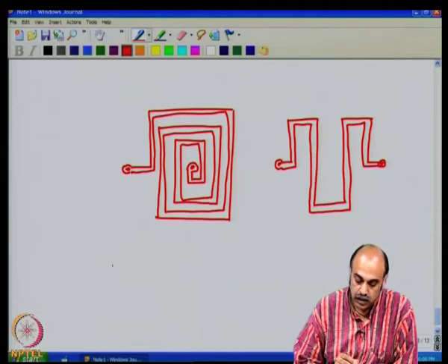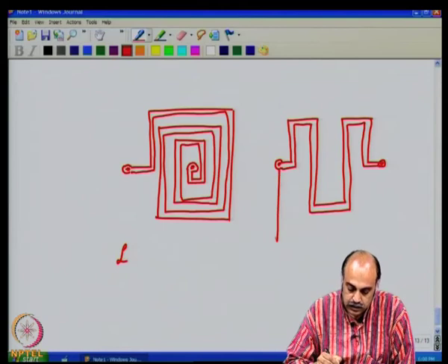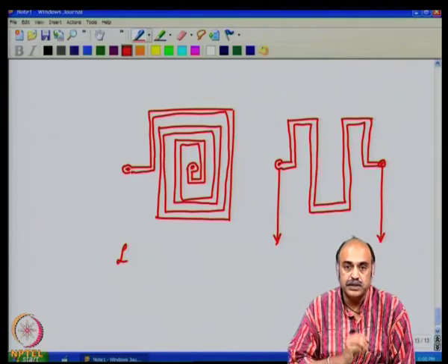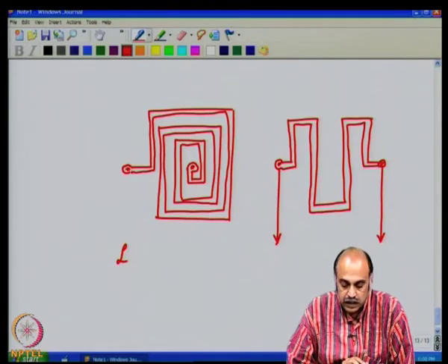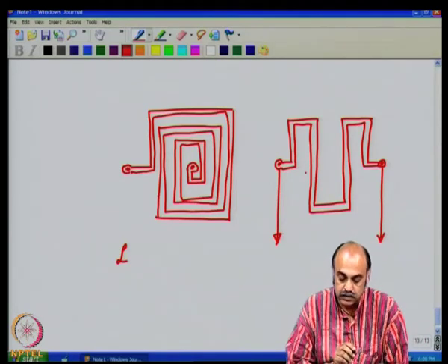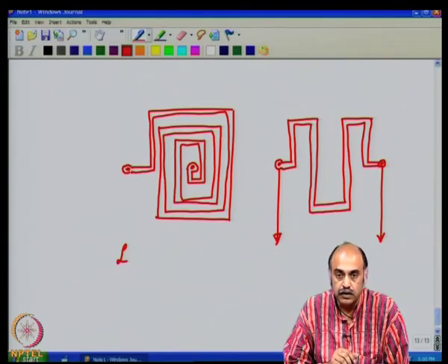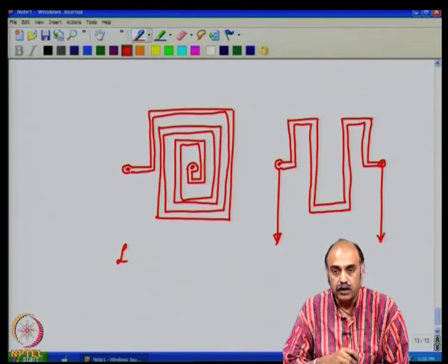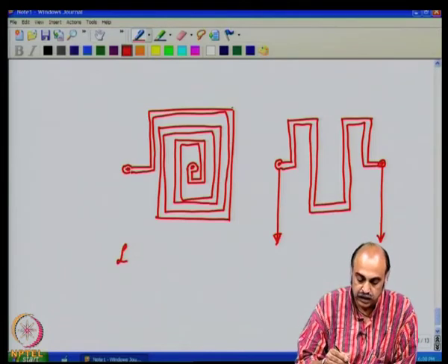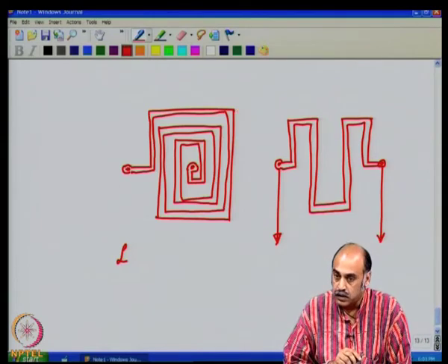So, like this you can make values of the inductors and then give these terminating pads to the impedance bridge and measure the value of the inductance. That would give you the inductance probably per unit length or per unit turn for a particular type of PCB laminate, and the developer should start making charts out of it, and then over a period of time he can have nomographs to quickly design the artwork for the printed wiring board.